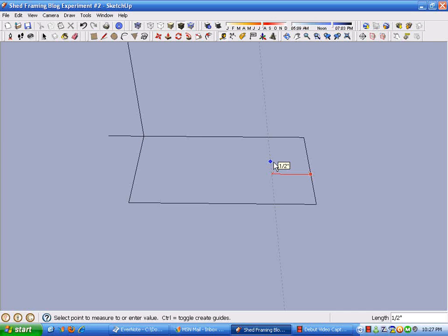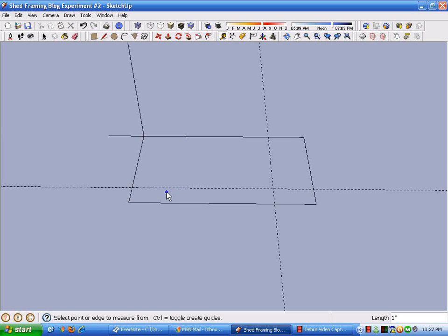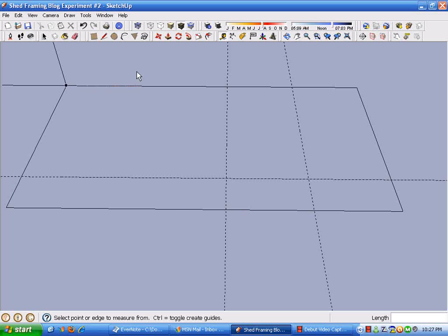We'll make a few reference lines here to create the molding. I'm going 1/2 inch over there, 1 inch over here. I think we'll give our molding, or the OG part of this, a 1/2 inch. And then we've got a couple of other lines that will form in here. This will kind of clear up as I draw along. I'm using the line tool here just to follow our reference lines. I know I'm going to have a 1/16 inch step in the molding there.